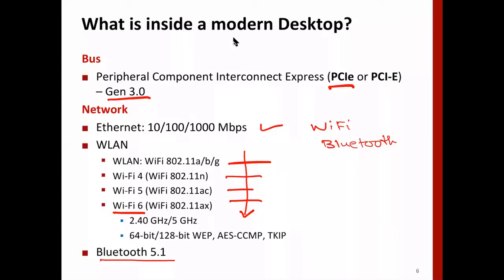The range of Bluetooth is quite less, up to 5 meters optimally. Yes. What else? Both points are correct. The data rate for Bluetooth is like 1 to 2 Mbps, but Wi-Fi has quite a big bandwidth. That's also correct. Something more? The frequency range is different. Yes, that's also correct. Energy usage, maybe. Sir, Wi-Fi allows you to connect to the internet, but Bluetooth can't. Repeat: Wi-Fi allows you to connect to the internet, but Bluetooth doesn't.